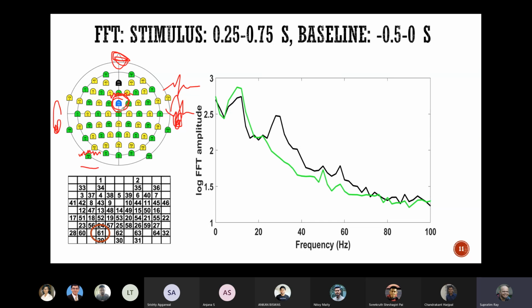But at the same time, if you put it too close to the electrode, then essentially you are cancelling out the physiological signal as well, because whatever this electrode is catching, suppose if this was the reference, the neighboring electrode, then it would more or less catch the same thing and then everything will get subtracted out.